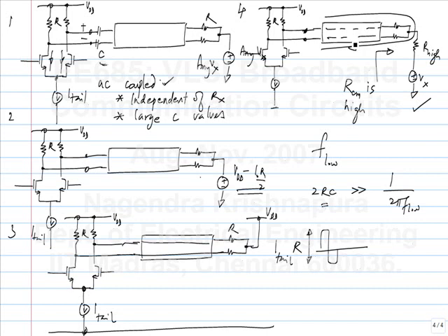Why? No, we are not. This is a differential transmission line. So the differential termination is the same in every case. The common mode impedance is different, but the current flowing differentially will be the same in all the cases. So the swing will also be the same in all cases, right? So there is nothing to distinguish. We are comparing identical transmitters that drive identical signals. So the distinction will come in other aspects.